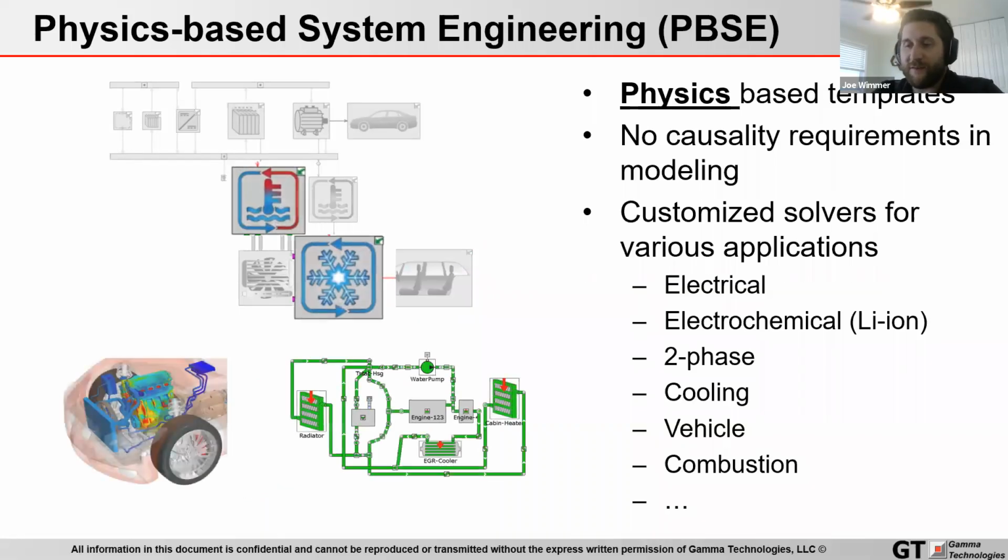On top of that, as I said, we also have one-dimensional flow, and this is going to be able to put together all of those different pipes that are going around in a vehicle, whether it's connecting the radiator to the power electronics or the motor. All these different things can be set up. It could be the two-phase refrigerant loop. All this can be modeled and set up in GT.